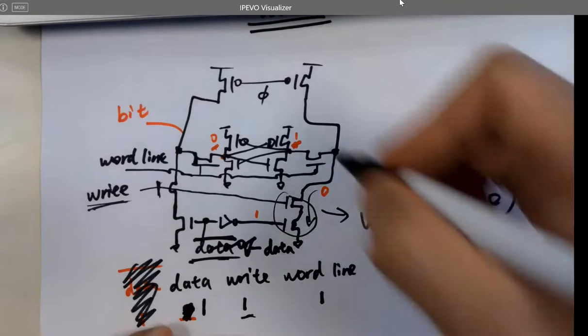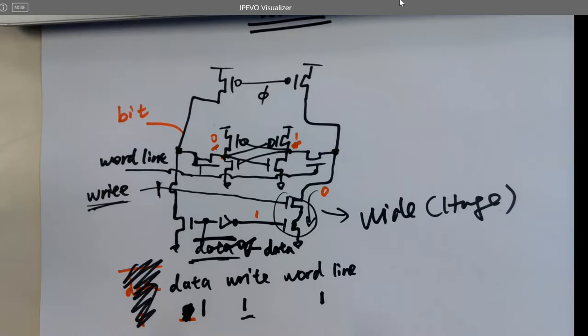I just have a hard time when I pick sizes for gates and stuff. I feel like I'm just picking values. Most of the time it all works for digital. It just depends on the driving capability. I think that's probably the only consideration when you are sizing them, just driving capability. But in analog, there are millions of considerations to size them. If you change a little bit, the gain changes and it stops working at all.